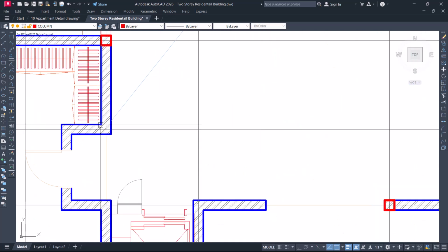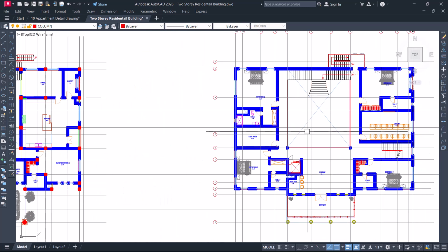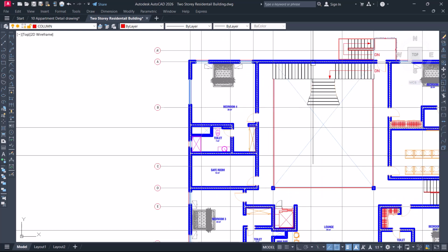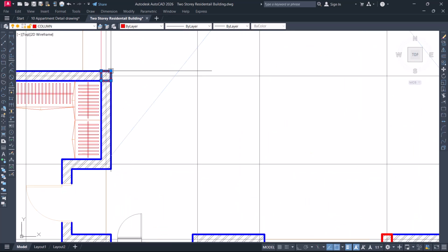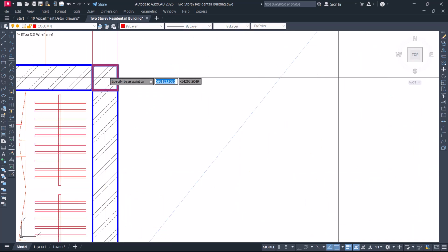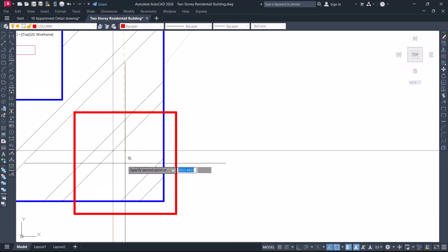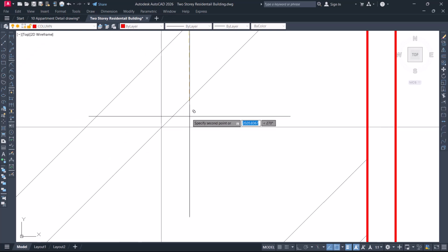Yes, that will be better because we are going to have cantilever slabs around this place, around this walkway, around the slab here. So we are going to have a column here. So I'll copy this column now, CP or CO, copy that, copy this. Now someone else can choose to do a different thing, but I want to put a column here in my own case. So I'll put a column here, then I will escape now.